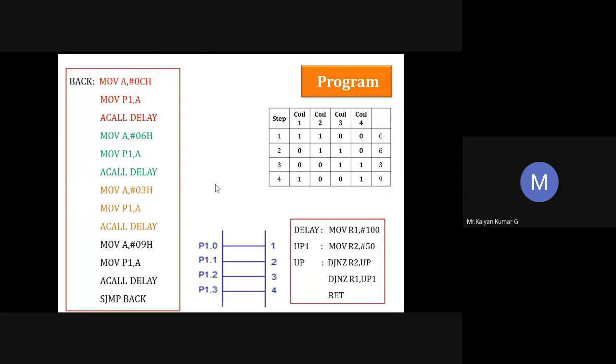So you have basically four ports: port 0, port 1, port 2, and port 3. Totally four ports are there. You have to take any two ports. Initially, you have to initialize one port as an input port, the other port as an output port. Let us take port 0 as your output port, and you have to set port 2 as your input port.